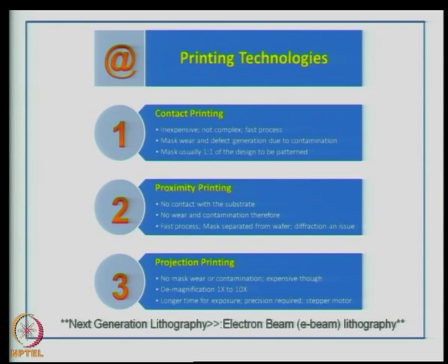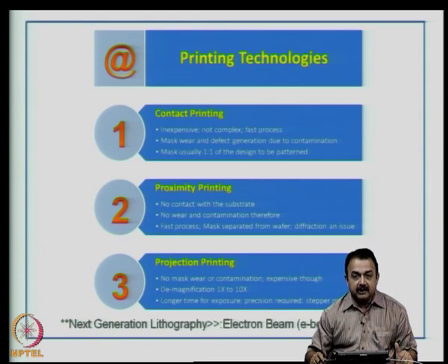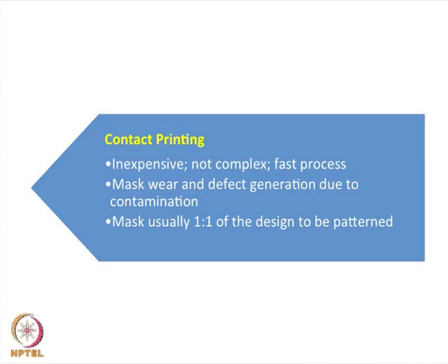Now, another point I want to mention here about printing or photolithography is that the printing technologies have improved day by day. The first thing is contact printing. That means, you have a film, you had another film on top of it and take the image. That is known as contact print.